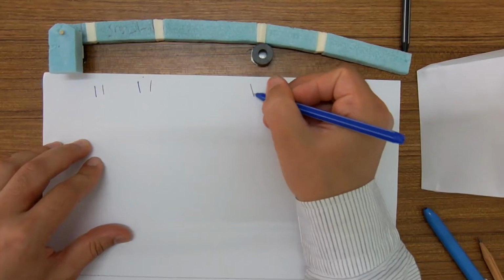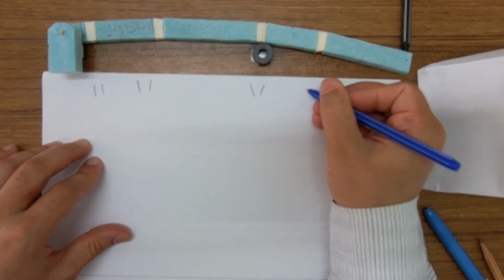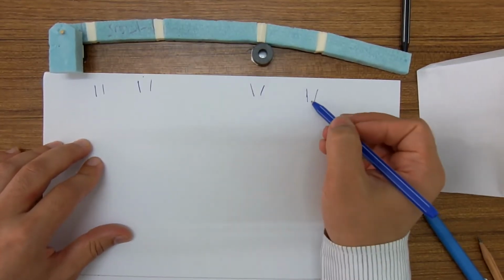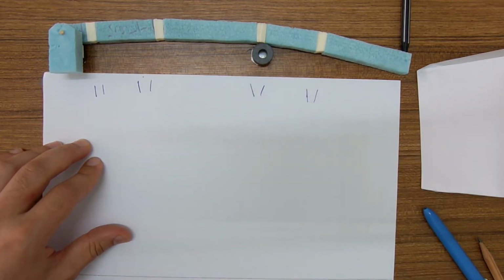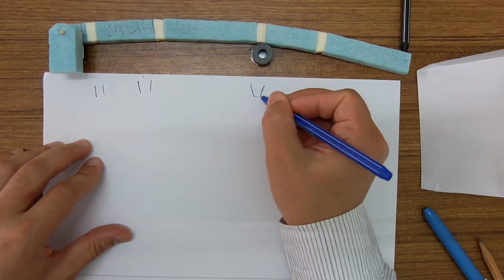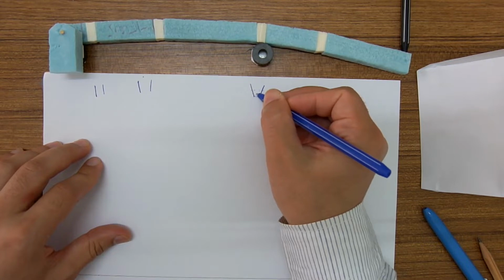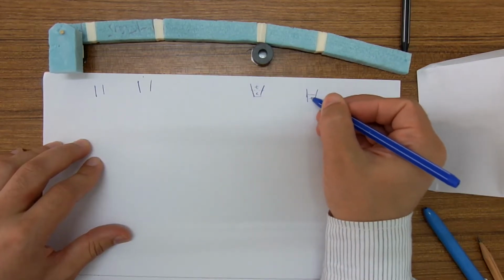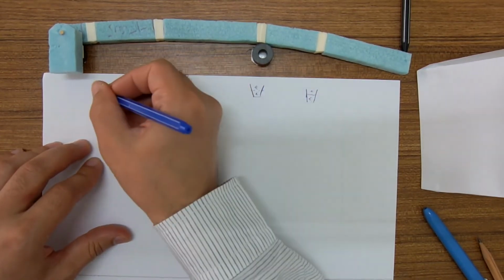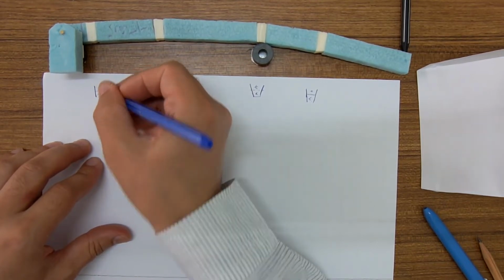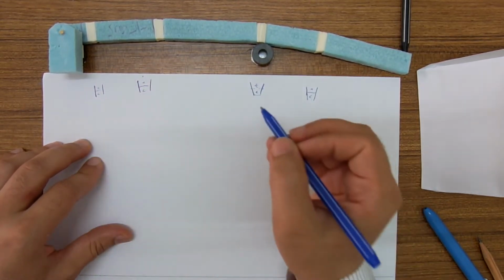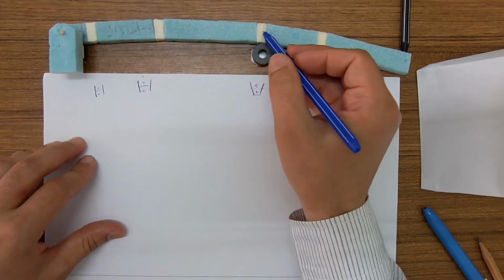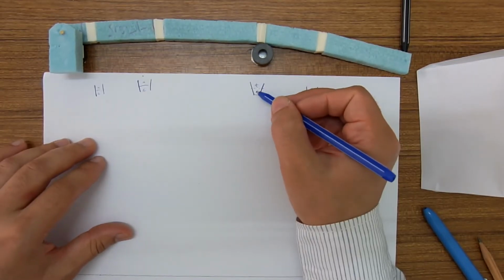Here it is worse. Here it is again not parallel, but is not as bad as this one. So at the bottom half there is compression. At the top half there is tension. Here compression, tension, compression, tension. Same, but it is very small here. The values are very small in this one. The maximum among these four occurred at this section because the deformation is more.